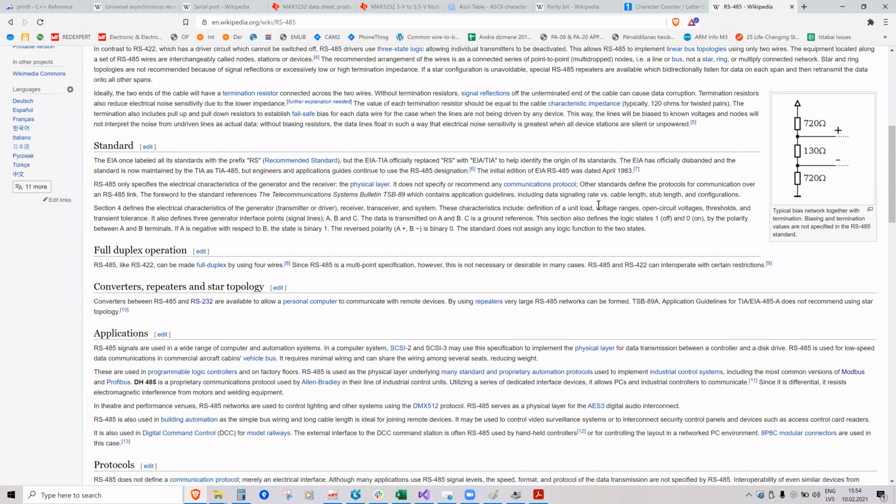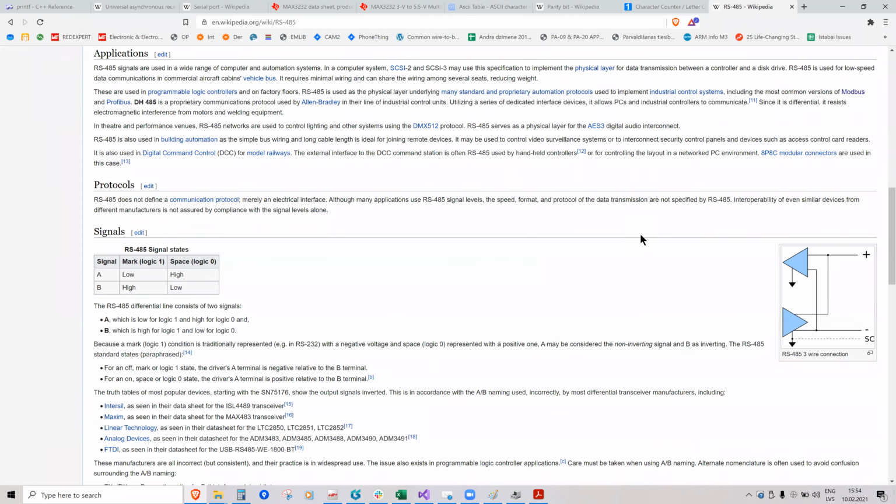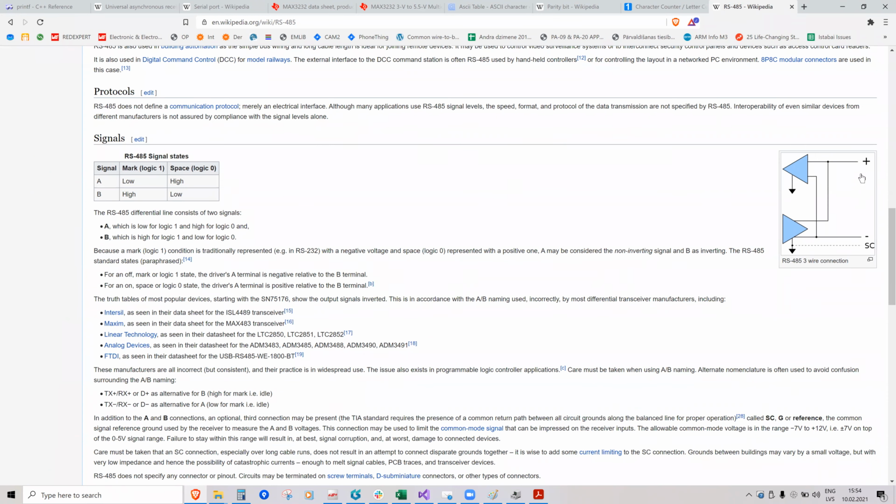But the disadvantage is only one device can speak at the same time. So usually either you send data rarely, so two devices don't talk over one another, or one of the devices is the master, which just asks questions to devices using, for example, a device unique ID, and then only the selected device with the appropriate unique ID responds. So you have kind of a network here.